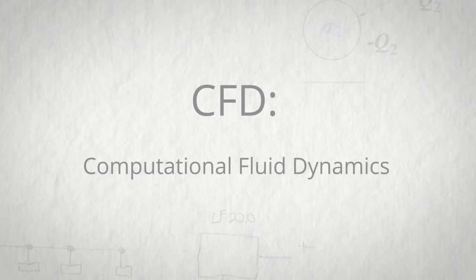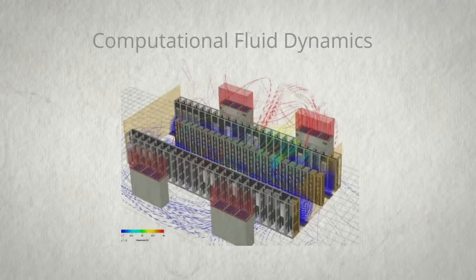One thing that we found very useful at Google is CFD analysis to see where your hot spots are and how your airflow is going to actually be directed in your data center. By doing so, you can actually model the way in which airflow will go, and it helps you make very simple design choices to improve the airflow in your data center.